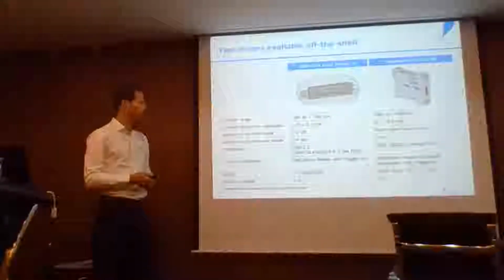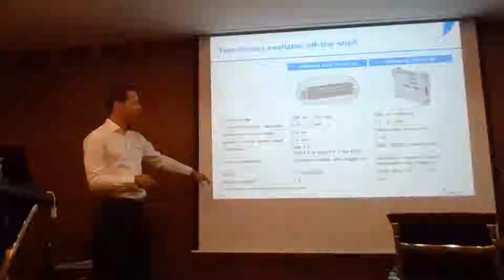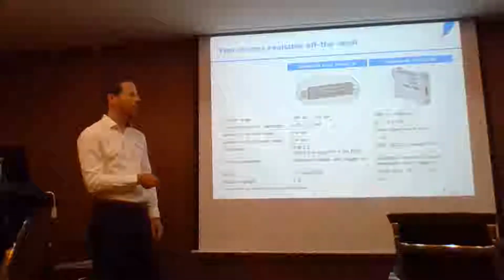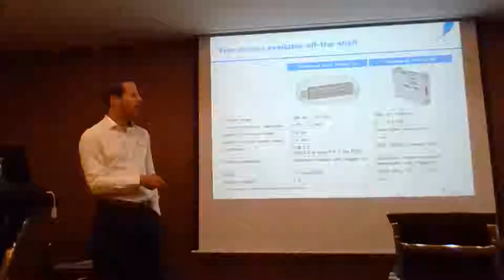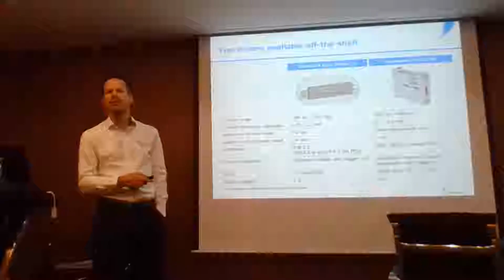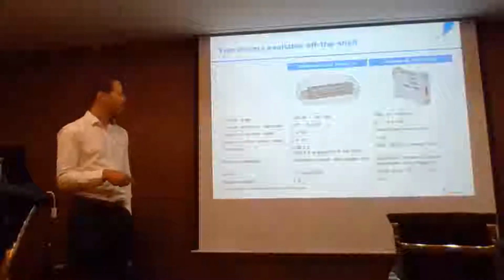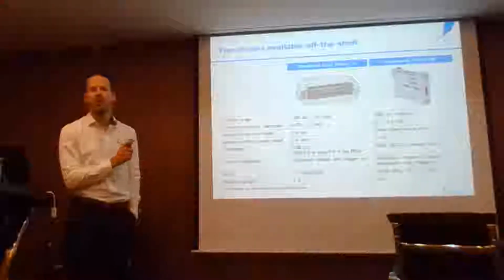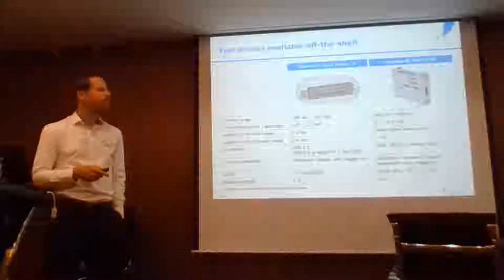Then, in terms of SDK, we just provide C# sample code, and there's a LabVIEW SDK which we can provide. For Gardasoft, there's a bit more. They have their own SDK. There's source code for more languages, so it's maybe a bit easier to integrate in the software. And important also, the supply voltage of the Gardasoft is 24 volts, so you need an extra power supply for that.